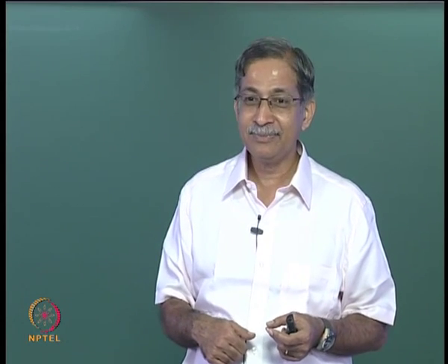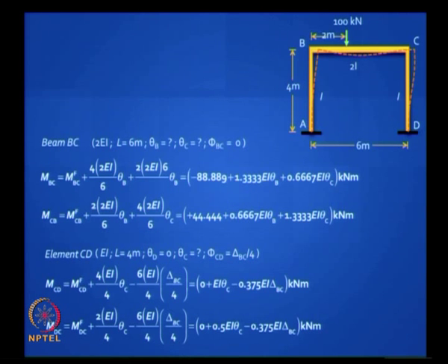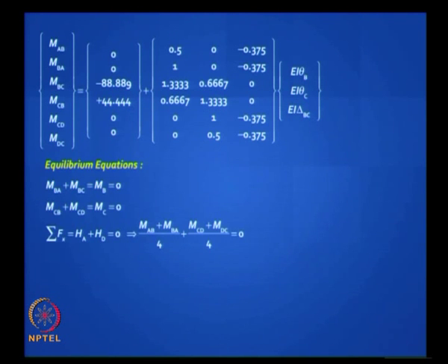Well, to make your life easier, why don't you look at it as horizontal reaction at A and D? What should those 2 reactions add up to? That's the easiest thing you can do. So don't break your head too much over it, that's all you need to do. Horizontal reaction at A and D should add up to 0, and for the sign convention we have assumed MAB plus MBA divided by 4 clockwise, where is that reaction pointing, from left to right or right to left?